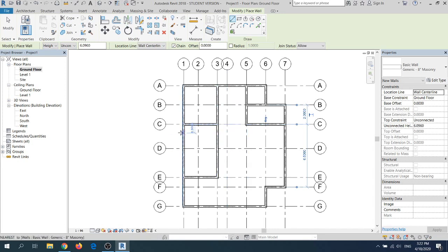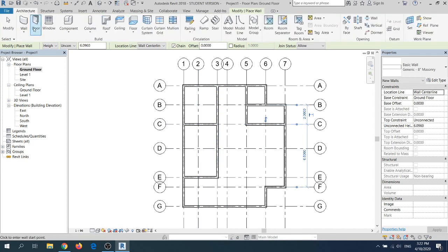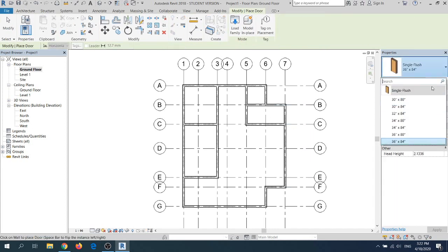After the internal and external walls are designed and done, then you have to go to the architecture tab again, click door and window in order to add the components accordingly. So for example, I want to add the door here. Then I would like to choose the door that I have in the library here, because in the next video I will teach you how to import the component or properties accordingly. So today we just want to use the simple library given by the software itself. So I have to choose a relevant item that fulfills my requirement.